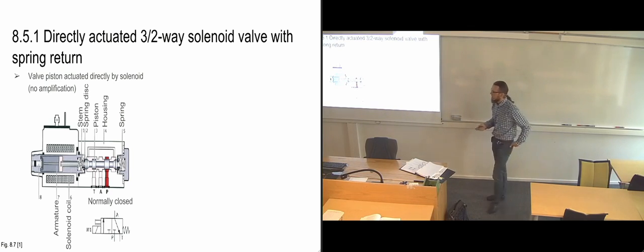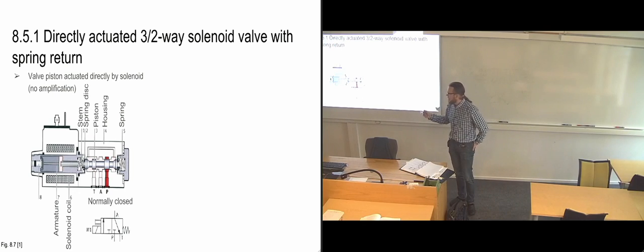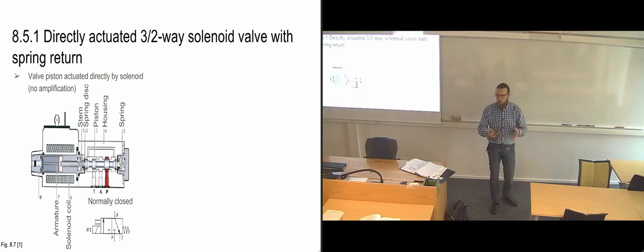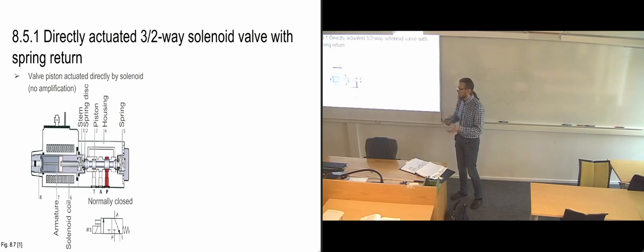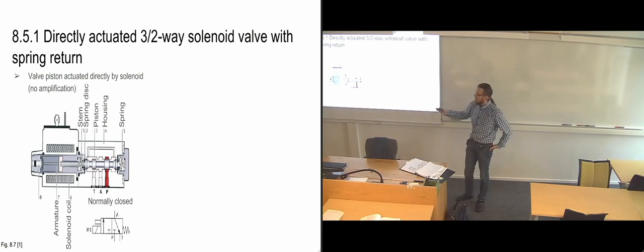So this is basically a magnet. It's not a permanent magnet necessarily, but it's a material that's going to become very magnetic once it's subjected to the magnetic field of the electromagnet. So it's going to start moving. So when you send electrical energy into these coils, they're creating these magnetic fields around them, and that's going to start moving this whole part here over to the end, over to the side.